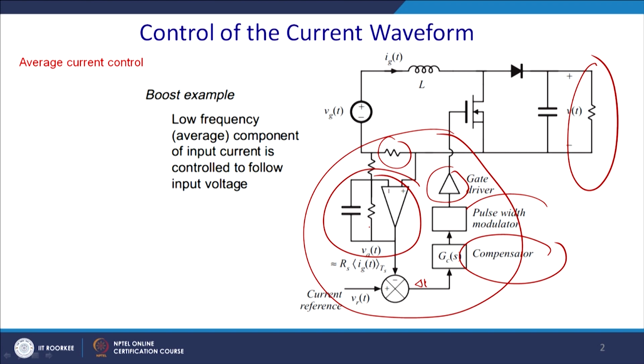You can have another mode called the peak current mode. There, instead of allowing the current to boost up, you work in a peak current mode, and that also has its own advantage. Each has its own advantage. Essentially, if you go by the stability analysis, it will be quite easy, because you have a compensator to ensure that the system does not go out of stability. So, let us see how this concept can be incorporated in a PWM rectifier.